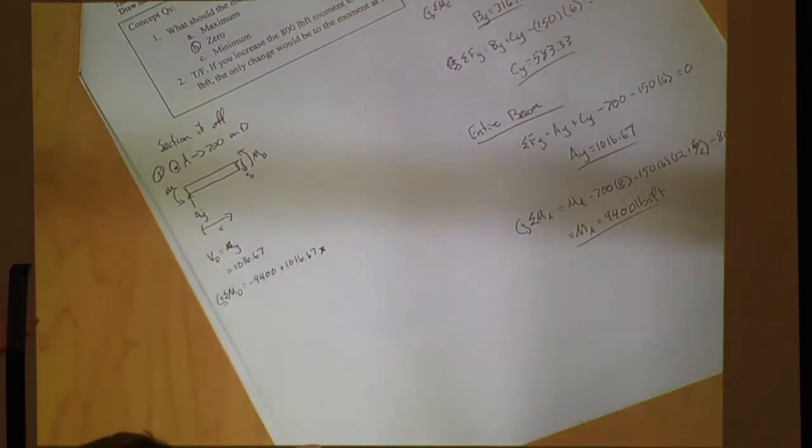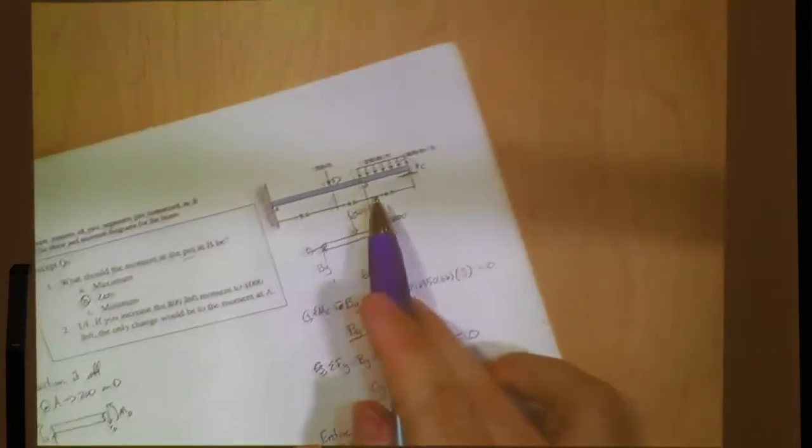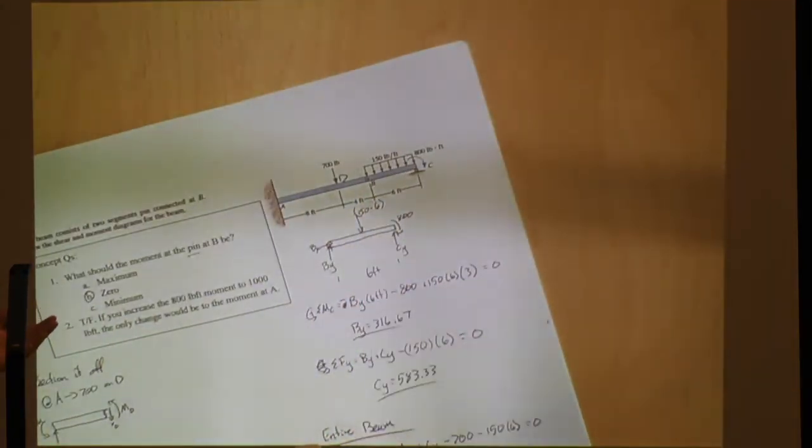So if it's an unsymmetric beam, where does it intercept the x-axis? A lot of the homework problems are all symmetric and rectangular loads, so you're just like, oh, it's right in the middle. But now this isn't symmetric. So where is it going to intercept the x-axis? Because when it intercepts the x-axis, what does that mean? Yeah, that's the max moment.